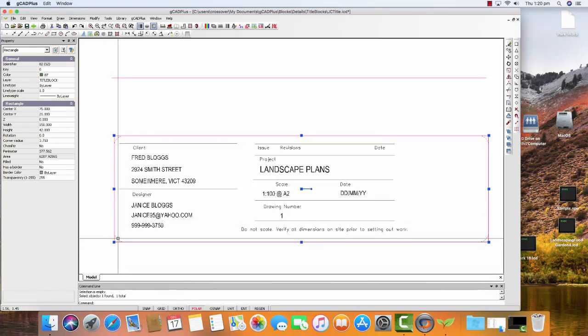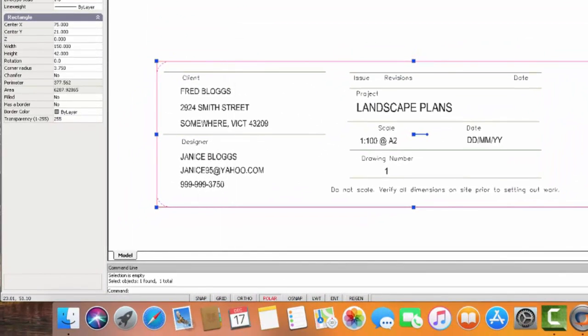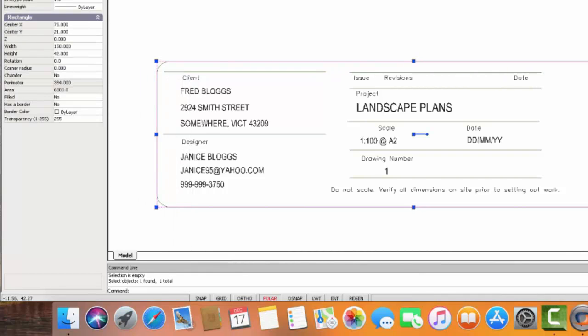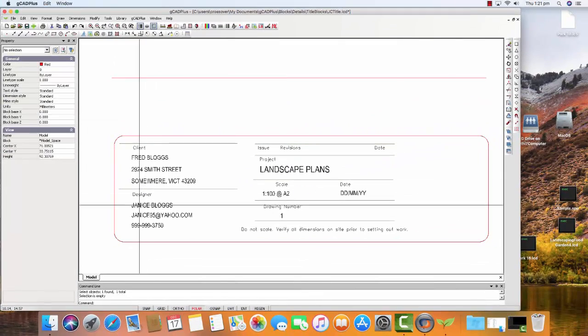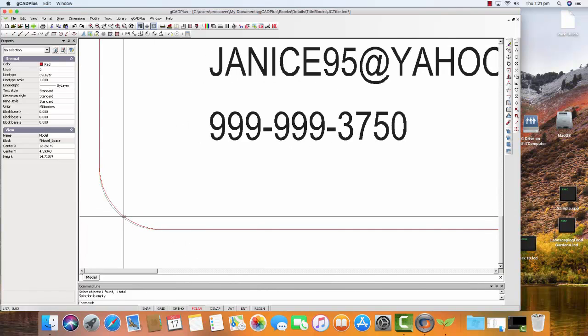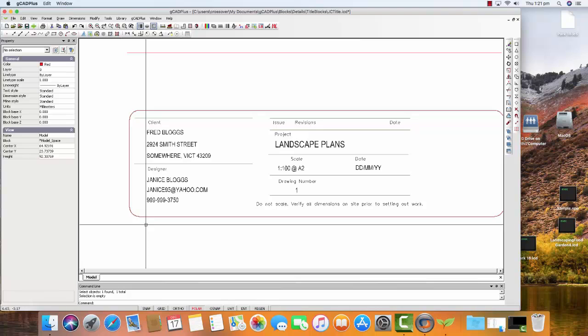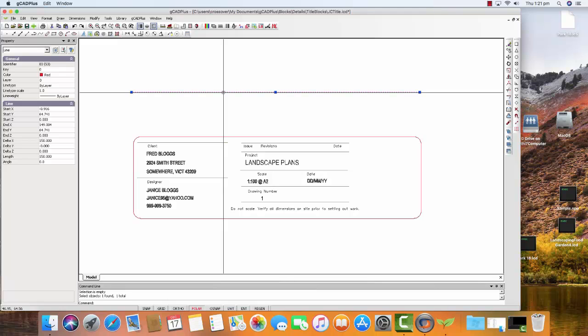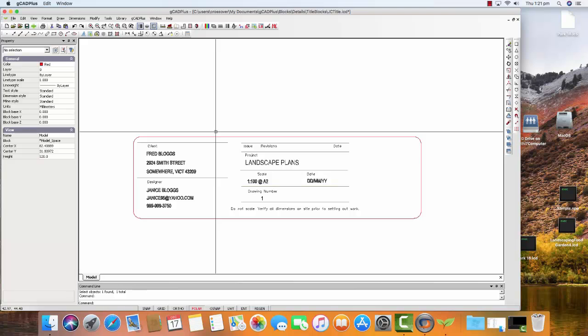The green rectangle that's underneath has a corner radius of 3.75. So to get that rounded effect, we'll make the radius 4 just to distinguish it from the other one. And they should now be slightly different there. The radius in the corner is slightly different. So it's really quite easy to start developing your drawing, which is going to contain, let's erase, that's going to contain the logo that we developed.